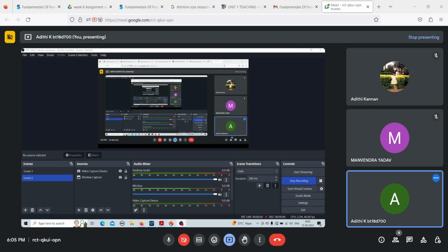Hence, Rittinger's law: the energy required is proportional to the surface area and not the linear dimension. So statement 1 is false. Basically, I am substituting m as 2 here. So you have dE by dx is equal to minus c x bar minus 2.